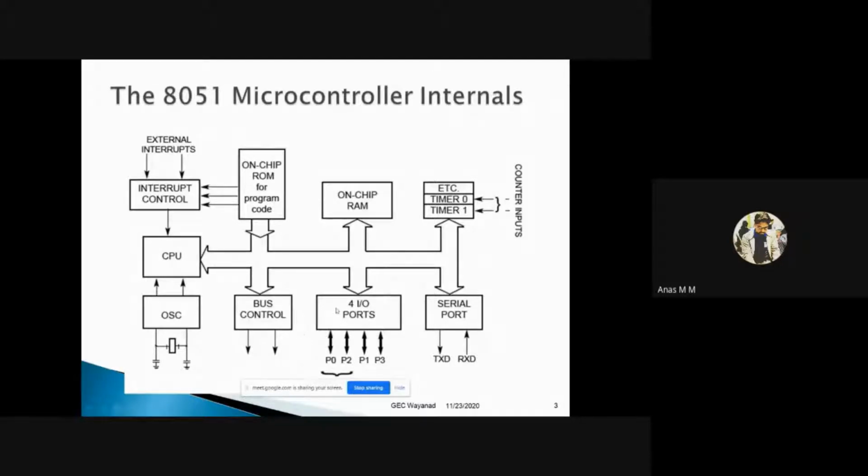We've done different programs using input-output ports. We created waveforms also using I/O ports. Then we did programs using timer 0 and timer 1 for creating delay and for the counting operation. So this much of the architecture we completed. Now we need to complete the interrupt portion and the serial communication port. These two sections are remaining in this hardware.